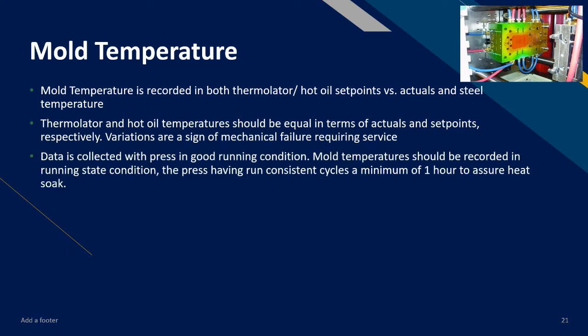Data is best collected with the press in a good running condition. Mold temperatures should be recorded in a running state condition, and the press should run a minimum of 1 hour of consistent cycles to assure proper heat soak.